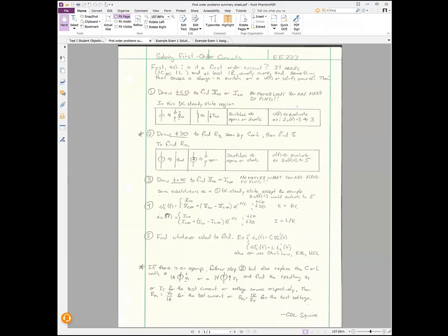That's because in step 4, you're going to substitute it into this equation. If there's a capacitor, you're going to use this. If you find any other initial condition other than VC naught, it doesn't belong there, and you just wasted time. And you don't have enough time in this test to be randomly finding stuff that doesn't help. If you haven't really internalized this, you haven't done enough problems yet. You've got to just keep going with these things until you know what this is.